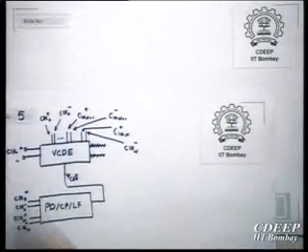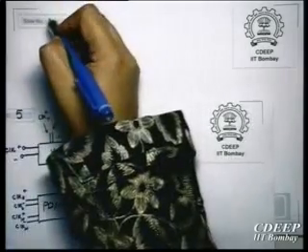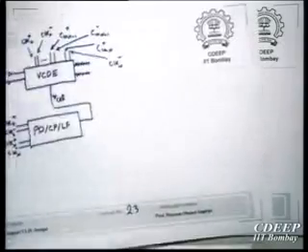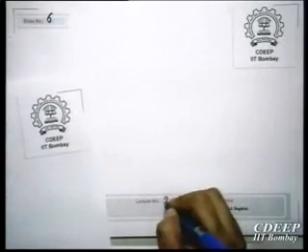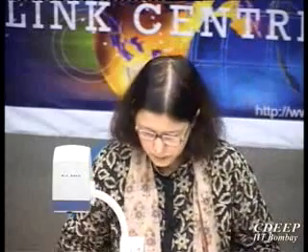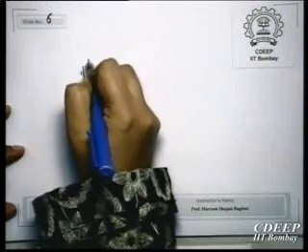But we can have differential delay elements also, everything similar according to that. Because if you have a differential inverter, then you can make a differential delay element. So starting from a simple cross-coupled latch, okay.